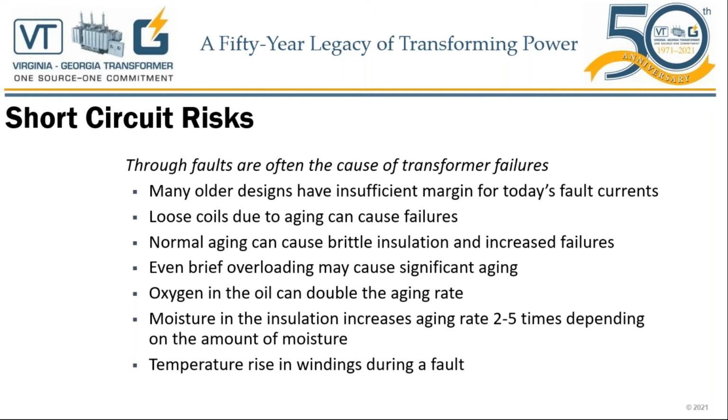So let's look at some of the risks. Through faults are often the cause of transformer failures. I think I said that enough already. Many older designs have insufficient margin for today's fault currents. Now, some of you may say, no, older transformers are better. Well, I agree and disagree. The agreement is, yes, I have seen 80, 90, 100-year-old transformers still running in the field. But I also know the help of the computers and the software allowed us to see the magnetic fields and have better calculations that we did not have back in those days.